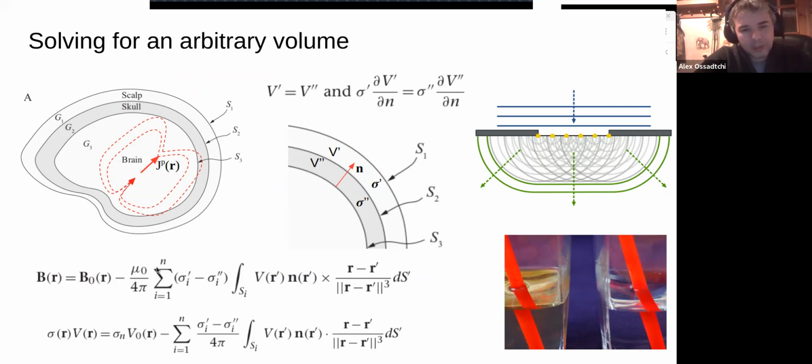Now this is just a summation that goes over each element on these boundaries, each element of the boundary between the media with different conductivities. Each element in this boundary is considered like a source, and this source itself is producing the magnetic field. You just have to sum up all these magnetic fields. You can ask me, why on earth do you have sources at the border of conductivities? Well, it's very simple.